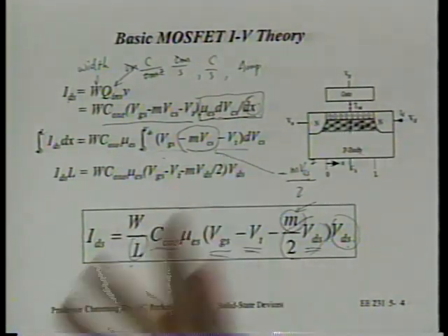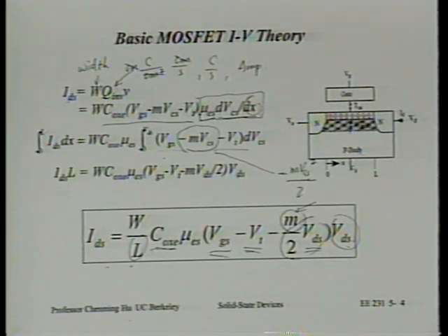That's why we don't like bulk charge effect. We prefer not to have that back capacitance, all right? If we can get rid of it, that's great. A lot of people don't realize that when they see this retrograde, they think that's something we put in to give us a better transistor, give us more current, make the circuit faster. Well, it doesn't quite do that, at least not in this manner. But it does allow us to make the gate smaller because it helps us suppress the short channel effect, okay? But it actually cuts down on the IDS, so we don't like that, right?